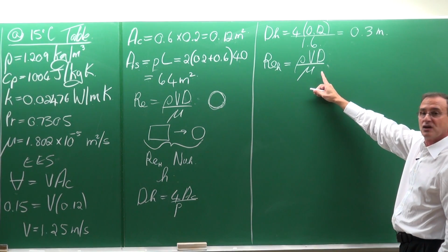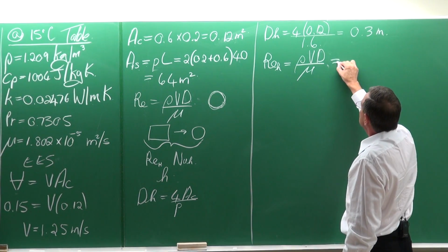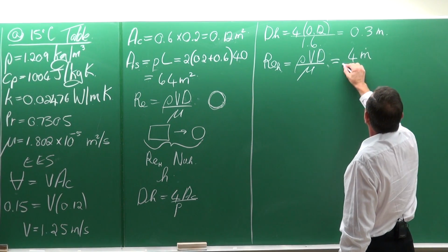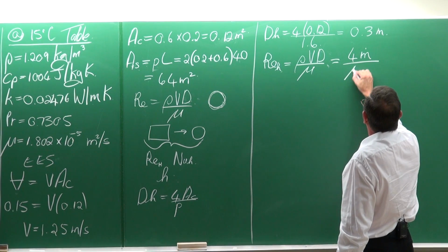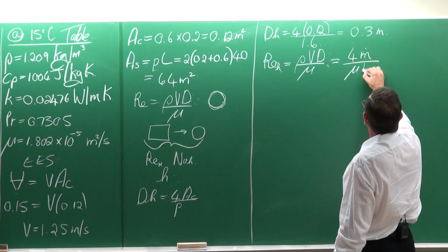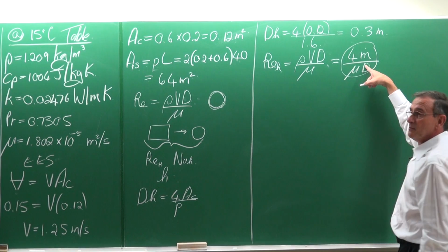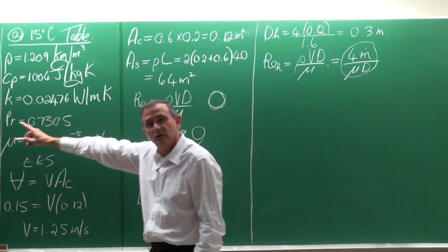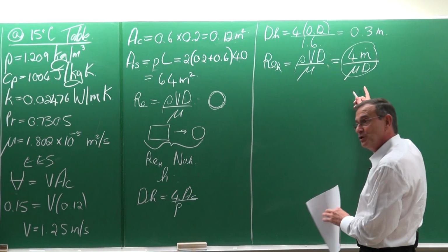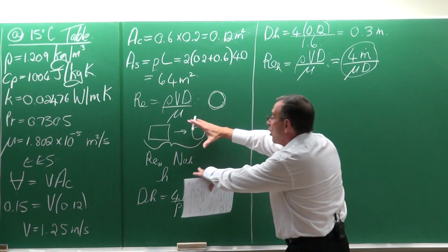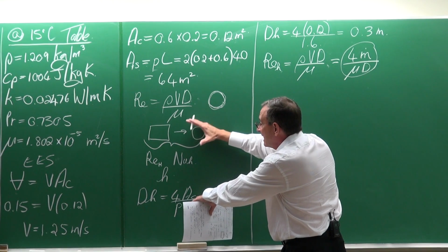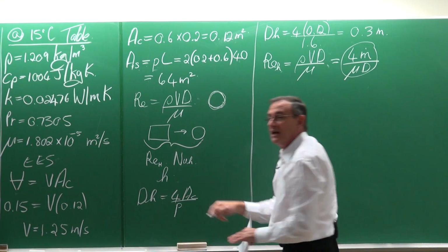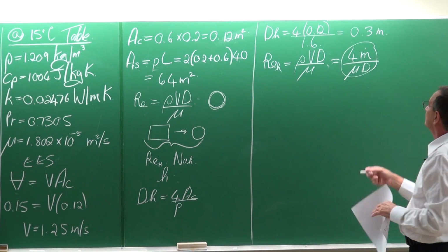In the previous lectures, I've brought to your attention that there is a derivation where you can say the Reynolds number is equal to 4 times the mass flow rate divided by the viscosity, and I think d or something like that. Remember, this is just valid for a circular tube. We do not work with a circular tube now. Yes, we are doing this in terms of getting this, but the reason for that is just to get the Reynolds number and the Nusselt number.